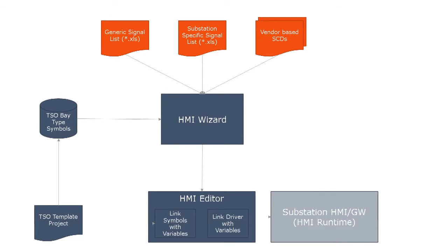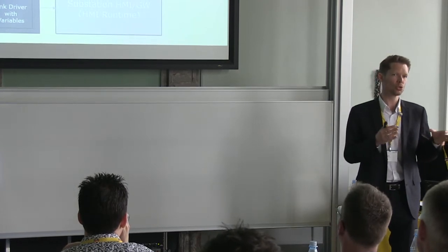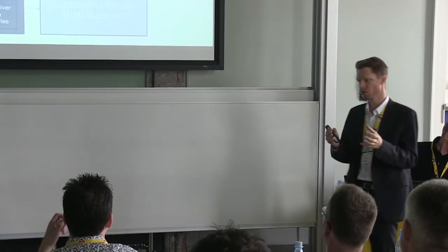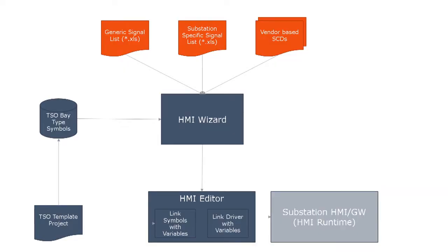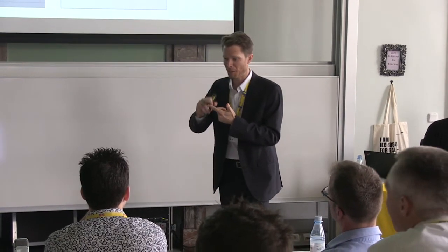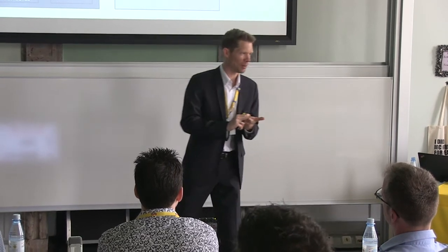Plus, there are vendor-specific SCD files or CID files or ICD files, whatever how you want to call it, but this information comes from the vendor-specific tools, not from a central system configuration tool. And in this case, this wizard here needs to do a lot of work, parsing all the big Excel files, working with always changing formats in Excel files.